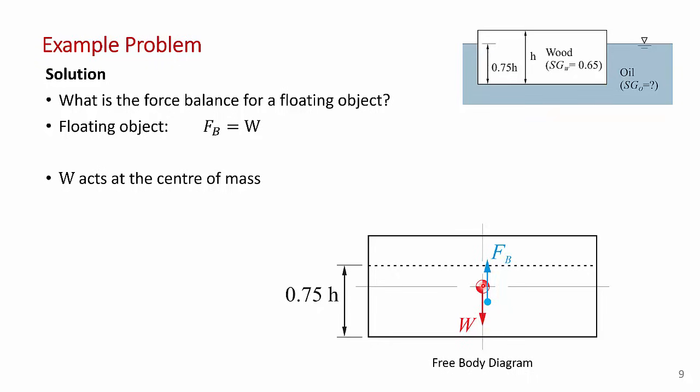So right there. In contrast, the buoyancy force, now it's not important for this problem, but it will be for subsequent analyses, to recognize that the buoyancy force acts at the center of the displaced volume. That's this blue area here. So you can see it acts slightly below the center of gravity here. And of course, it would act on the center line, but I've just shifted it off so you can see the location of the buoyancy force.